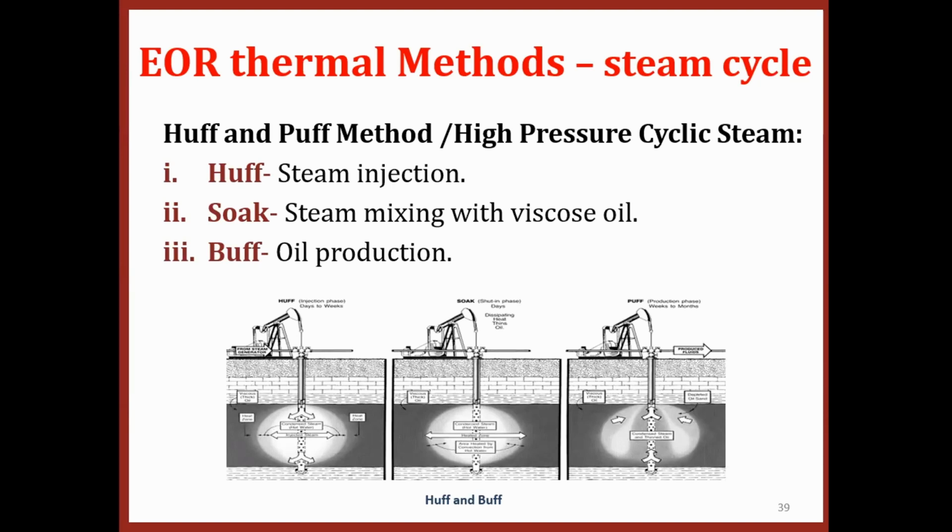This kind of tertiary recovery is suitable for heavy oil, viscosity more than 200 centipoise, for shallow wells, not very deep wells, could be 1,500 to 2,000 feet depth. And low production, you produce about 200 barrels per day from the well, which is not bad because now you can make money.